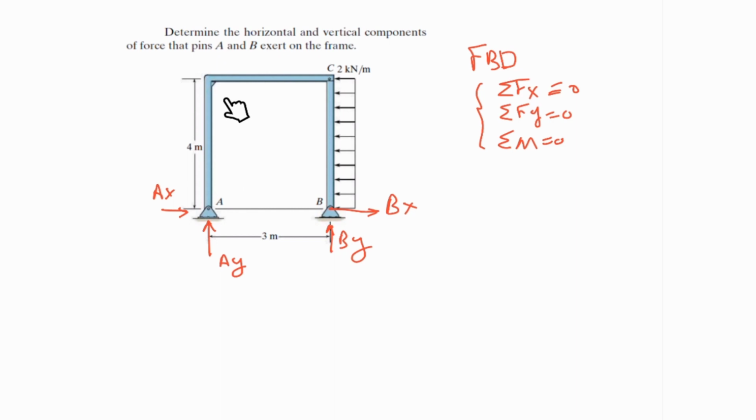And the point of two-force members is that instead of two unknowns, I can put one unknown here. Because of having a two-force member, I know the direction of the forces applied on point C and point A, meaning that only the magnitude is one unknown, and in total we would have three unknowns. Okay, then I erase these things and try to show you how to do this question.